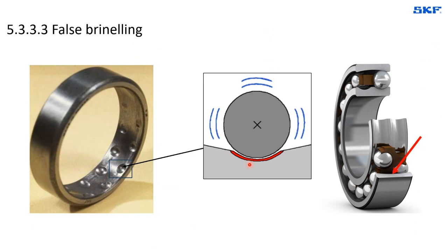There will be a wear process, removal of material, and the damage can be much more significant in ball bearings as compared to roller bearings, and also in bearings that are standing still as compared to bearings that are running.